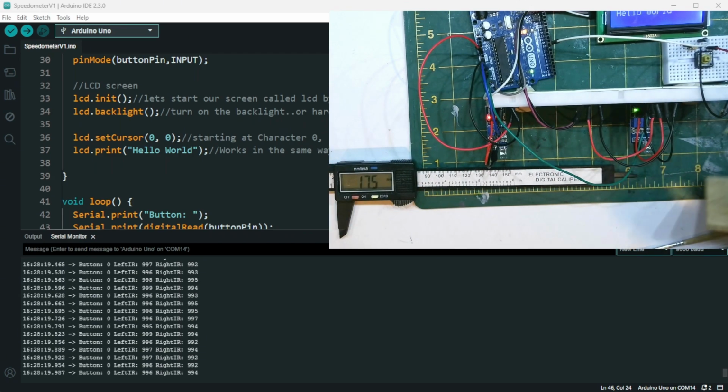Now obviously I'm doing it quite roughly at the moment. However, when I completed my own tests, I discovered after numerous tests that I could get the reading to be within about 0.5 of a millimeter. The other thing that I discovered was that at the moment I have the sensor in this orientation. If I placed it in an upright orientation, I found out that it was even more accurate, and I was getting to about 0.3 of a millimeter.